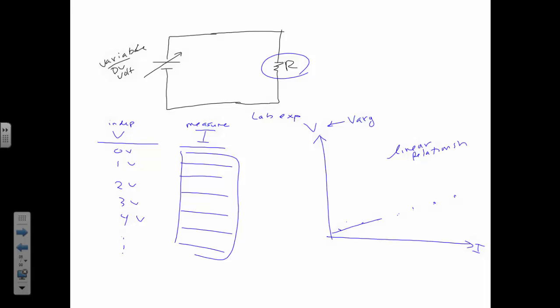And if you were to draw a line through this, if I were to take that resistor and do it, guess what the slope would be? My slope would be 385. So it turns out my equation for this line would be V equals 385 times my current, I. All right. Turns out this is my resistance, so I get V equals IR.